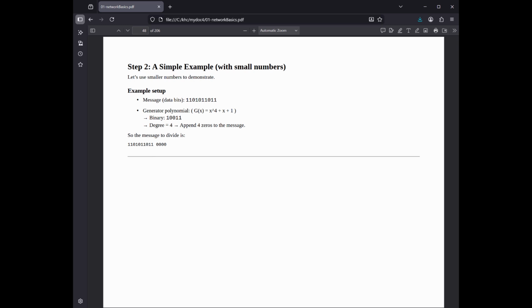1. Data preparation. The input data for the CRC calculation includes the destination MAC, source MAC, length/type field, and the data payload itself. For this simple example, we'll use our message 0x03. Message M, binary 11; leading zeros are often handled by initialization constants in real implementations to avoid issues. 2. Appending zeros, the mathematical basis. The algorithm conceptually appends 32 0 bits to the message, creating space for the eventual 32-bit CRC value. Augmented message: 11 followed by 32 zeros.